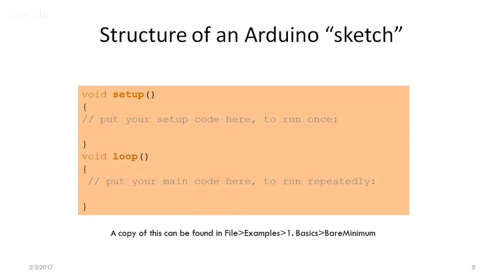In the case of making your input or output pins, we have to define them with the help of pinMode. If we define pinMode 13 as OUTPUT and write it HIGH, it will behave like a high output. And if we write it LOW, it will behave like a low output.